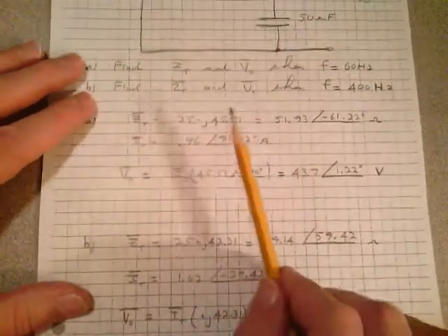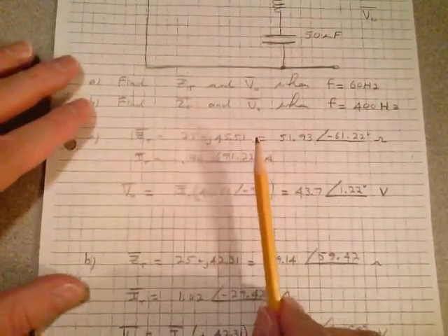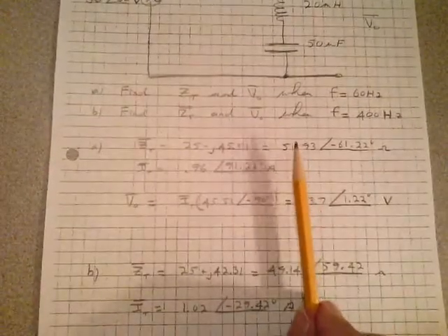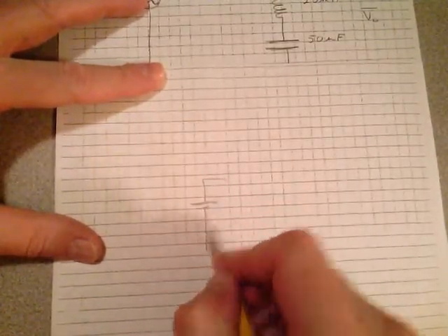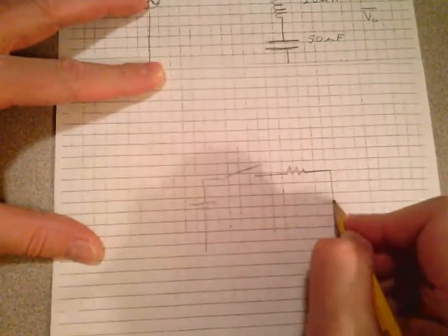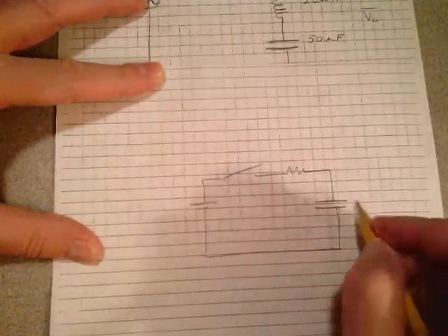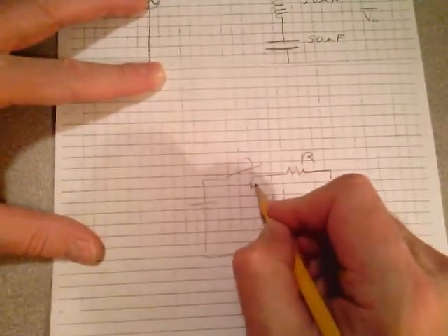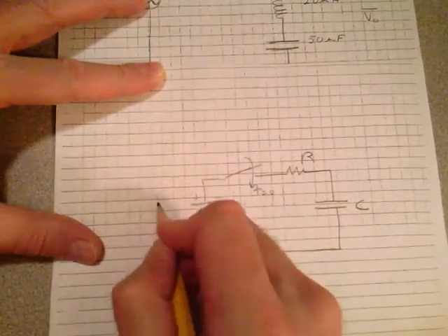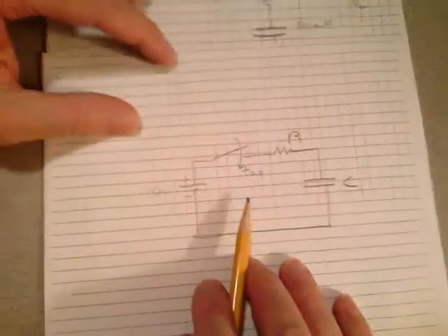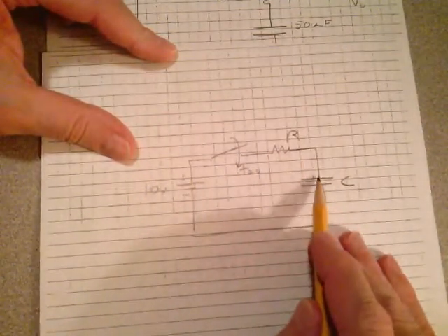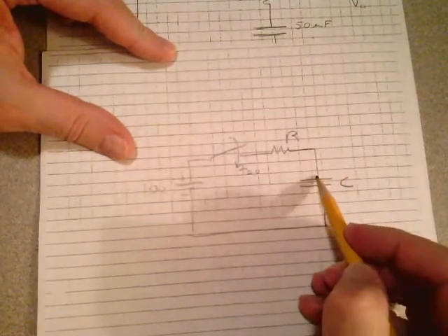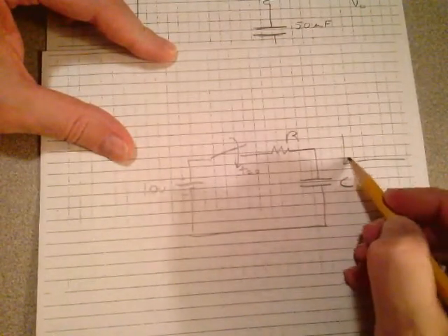Now, before I take a look at this in terms of sinusoids, which is what I want to do, and continue with this problem, I want to point something out here. Remember when we had these circuits, we had a step function, we closed a switch that looked like this. Let's just use the capacitor. Here's a capacitor, here's a resistor, and we closed that switch at t equals 0. We had some voltage out here. And we said when we first closed that switch, that capacitor looks like a short circuit because all the charge is trying to run to that plate. That charge builds up, and consequently so does the voltage, exponentially.